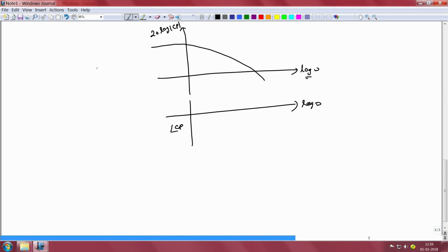So the omega equal to 0 cannot be located, but at low frequencies, assuming that the plant has a constant gain, then the Bode plot of the plant looks something like this, where the slope of the Bode plot changes near the corner frequencies of the plant. So if one were to draw the phase plot, it would start at a phase close to 0 degrees and then decrease and then continue decreasing further.